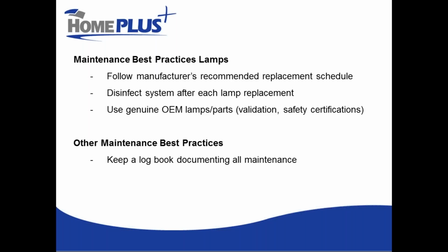Technically speaking, after you replace lamps, you should be disinfecting the downstream system. Now this will depend on how extensive your distribution network is after your UV sterilizer and whether or not you're already using chlorination. But disinfecting the chamber and any equipment between the UV and your chlorination system is a good thing to do every time you replace a lamp.